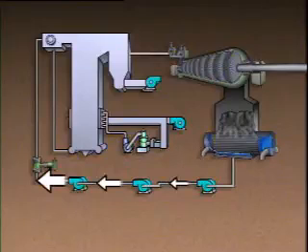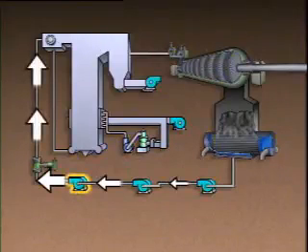By the time the water leaves the feed water pump, its pressure is high enough to overcome the pressure in the boiler, and the water is forced into the boiler drum. There is a relationship between steam flow through the turbine and the demand for electric power on the power generation system. This relationship is helpful in understanding why steam flow has to be controlled.